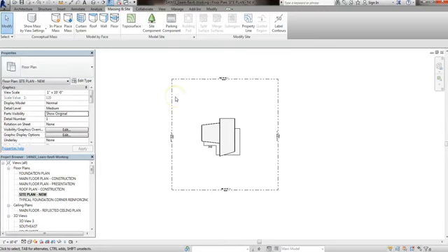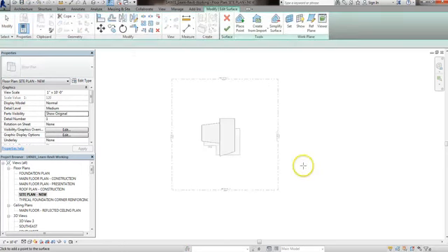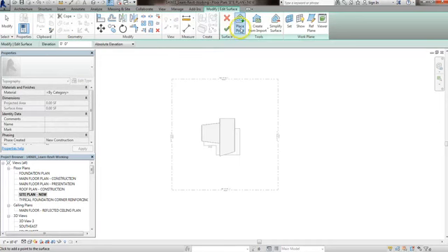If you can't import it from CAD, another way to do it is to import the image, and then you'll see the topo lines, and then sketch those topo lines just with regular lines, just with detailed lines. And then after you have that, you go to topo surface, and you're going to want to place a point. Okay. Our absolute elevation is going to be, I think, 6,100. Let's see if I'm right on this, or else I'm going to have to go double check my file. Then you start clicking points.